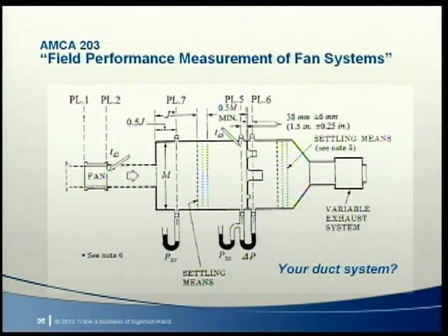Some designers want to verify fan performance in the field to make sure the fan works as predicted by the manufacturer's fan curve. I always think: does your duct system look like this test chamber? Because if it doesn't, the as-installed fan curves won't be the same as the catalog fan curves. And it's not easy to duplicate published fan curves in the field.